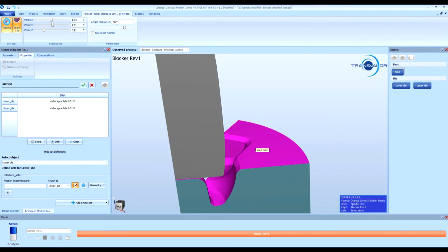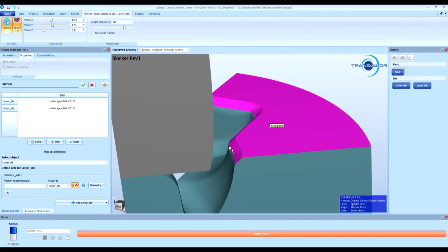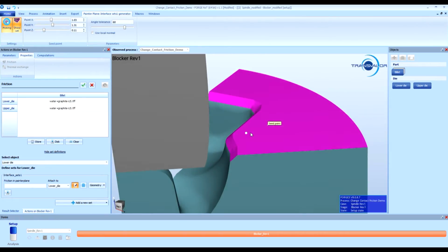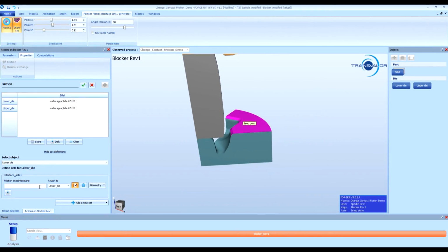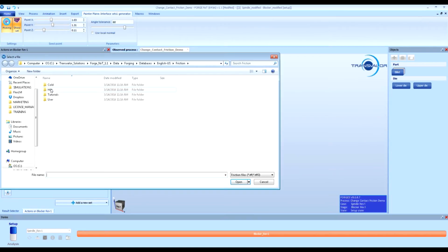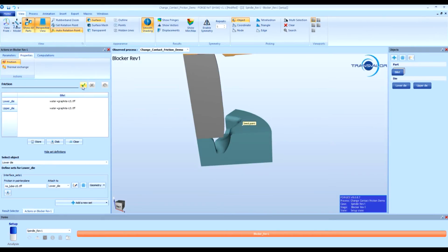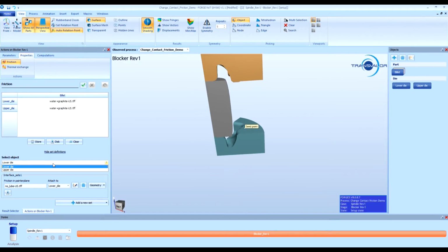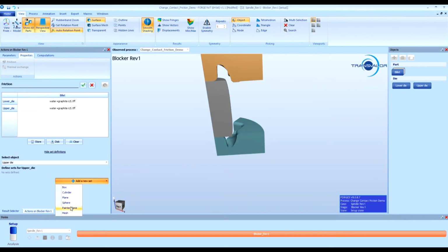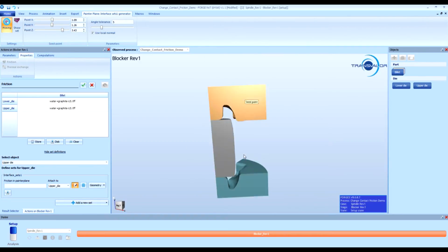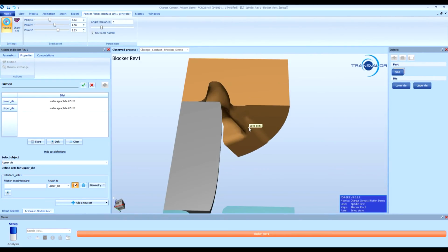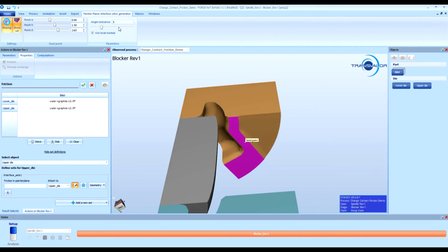selection using the tolerance angle between each normal of the surrounding elements. The local normal enables to propagate the selection by including new elements in the initial pool of seed elements. It enables more precise selection. The user picks the friction coefficient appropriate for the specific sprayed zone or specific roughness. Here we do not consider lubrication within the set. We repeat the same operations for the top die using the same tools explained earlier.